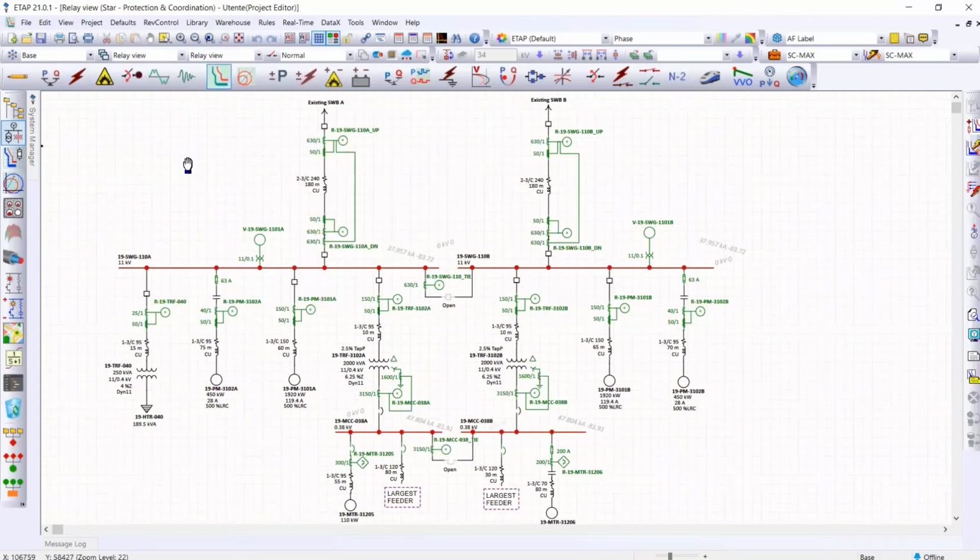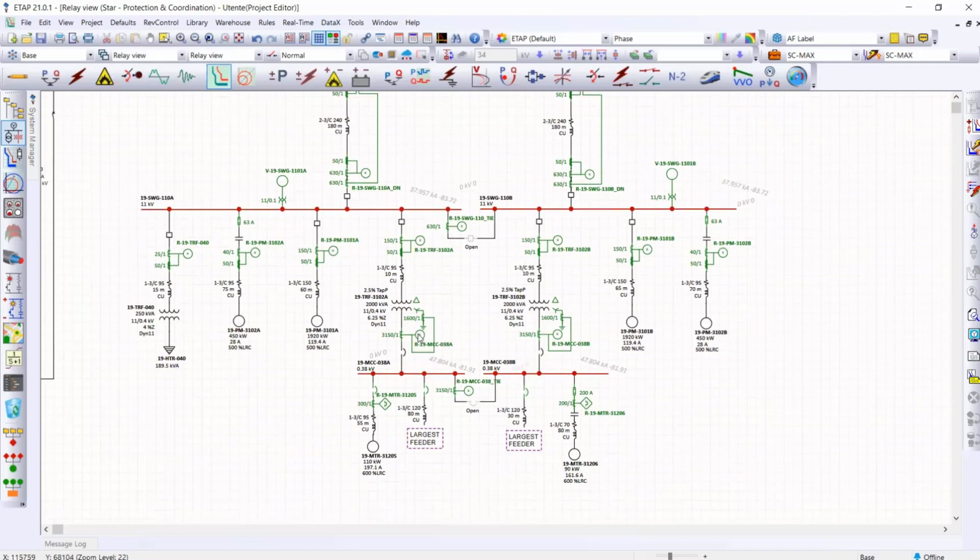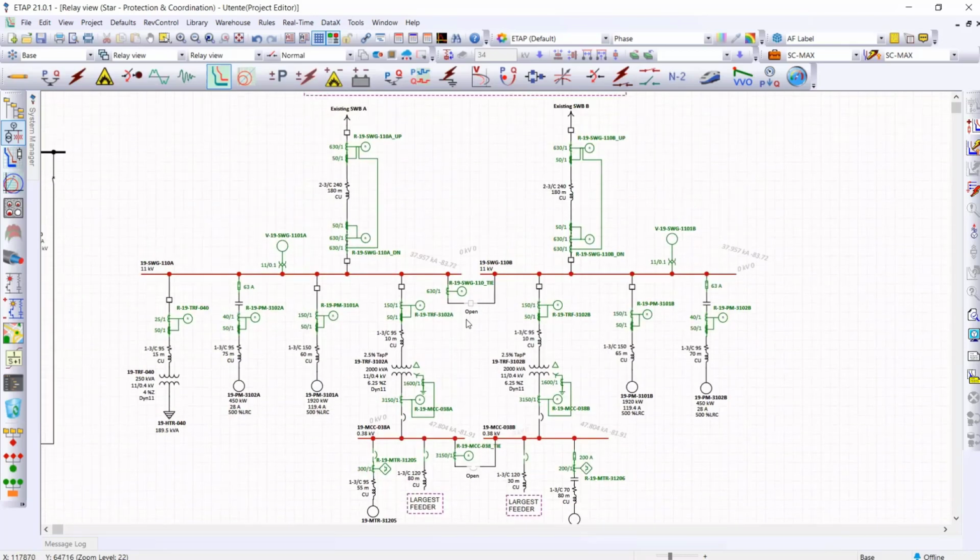The presentation has been prepared by our protection engineer with the scope to identify in more detail all the protection installed in this new substation and new loads. Basically, for the incomer, we have the phase and ground protection with phase and ring CT. We have the cable differential protection. We have the bus-tie protection, and all the individual medium voltage outgoing feeders with relays connected to phase and ring CT. On low voltage, we have relays connected on the incomer feeder and also at the start point of the transformer, and so on.